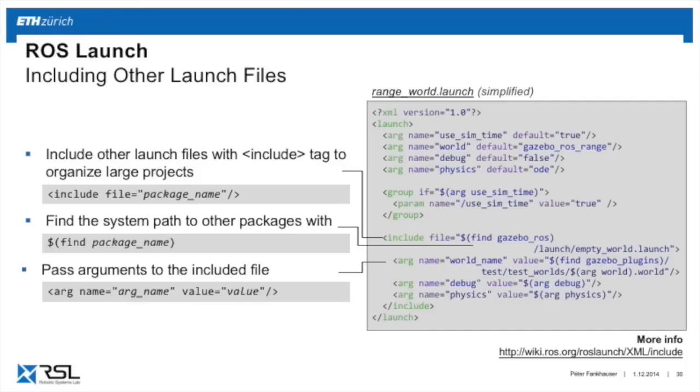Importantly, in ROS, don't use absolute file paths. If you give it to a friend, they might have a different username, etc. So what we always do is relate it to a package. In this case, it says find and then the package name. I've written here, this gives you the local absolute path, and then you would be in the launch folder, the empty_world.launch.